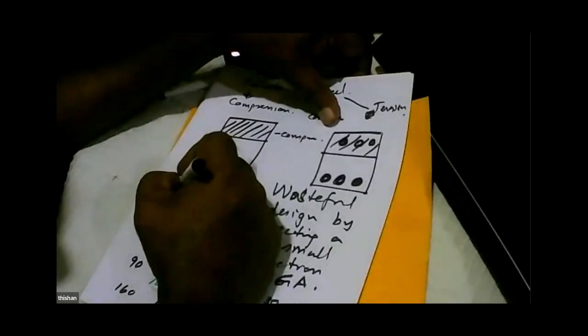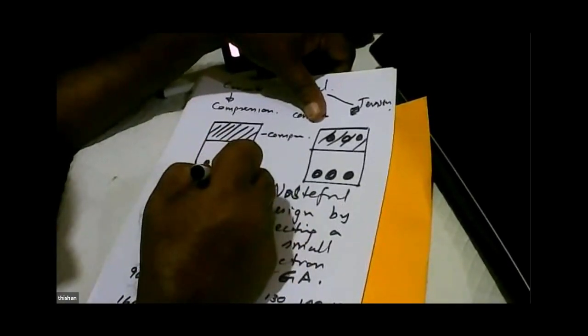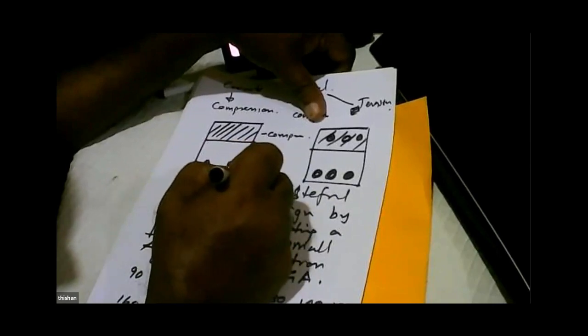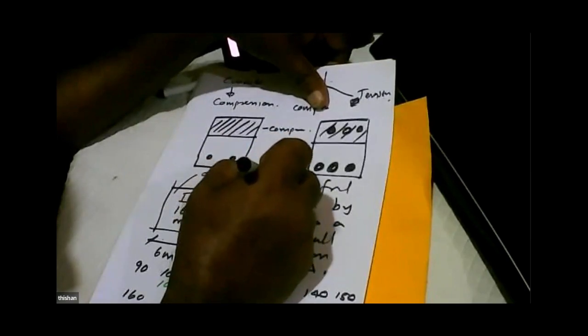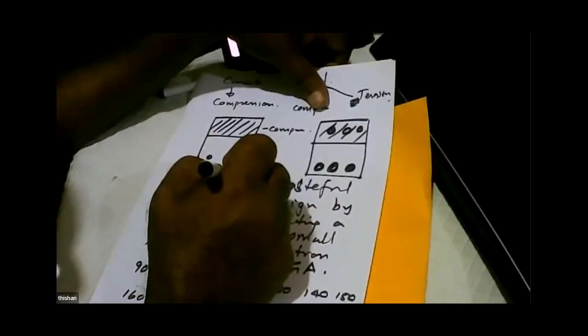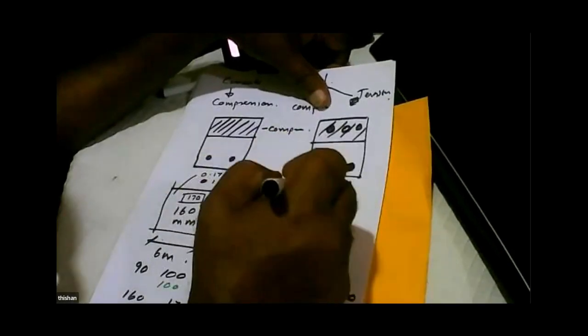So what would I know? Let's say I'm using 170 multiplied by 25 as the dead load. And then I would have 1 kilonewton per meter squared for finishes and services, and another 1 for partitions, plus an imposed load of 2.5.